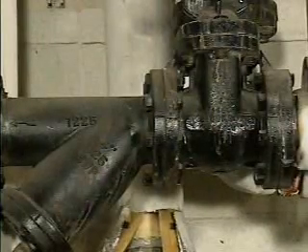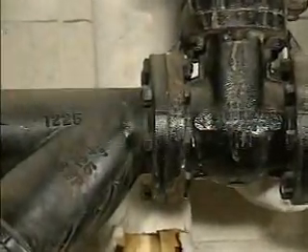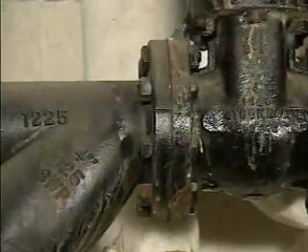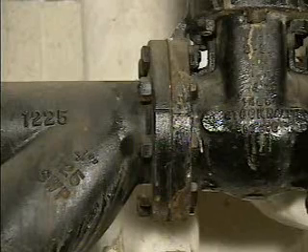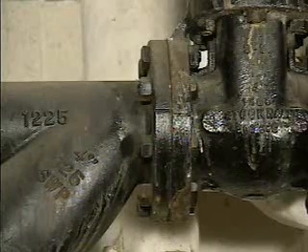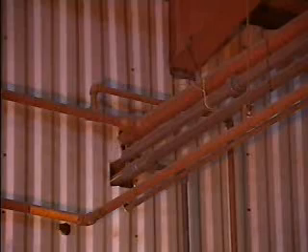and lift heavy loads. Another characteristic of carbon steel is that it's less brittle than other materials, such as stainless steel, so it's able to absorb vibrations. Therefore, it is well suited for systems that generate significant vibrations, such as in vibrators used to make anodes and aluminum manufacturing processes, lifts, and large gearboxes attached to motors or turbines. Because it is susceptible to corrosion, carbon steel is generally used with non-corrosive gases and liquids.